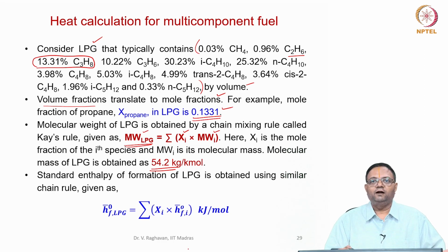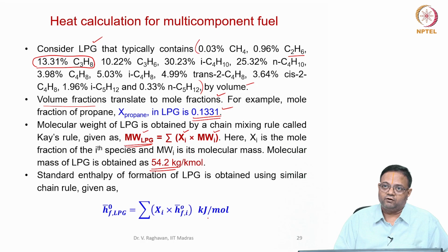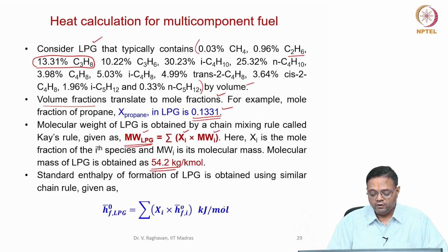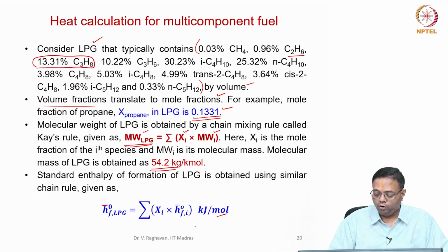So it is heavier than air. We have already seen this. So now the standard enthalpy of formation of LPG you have to calculate, because all these components have an enthalpy of formation, that also on a molar basis. When you say per mole, I can use a simple mixing rule based upon mole fraction.